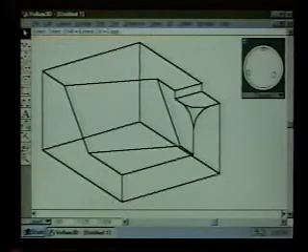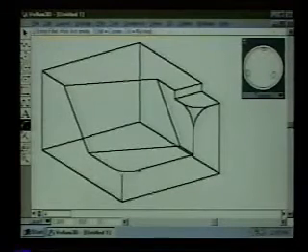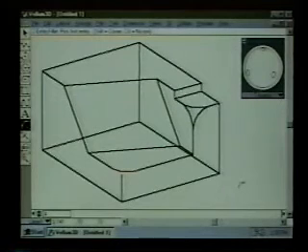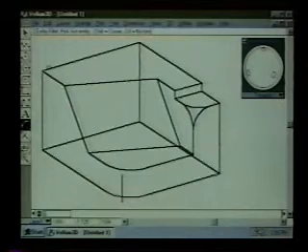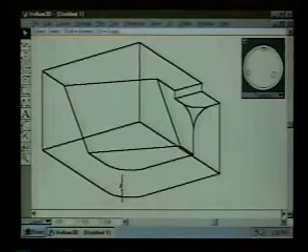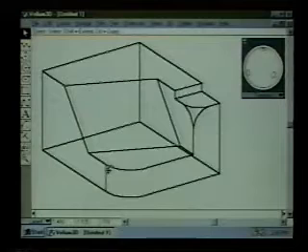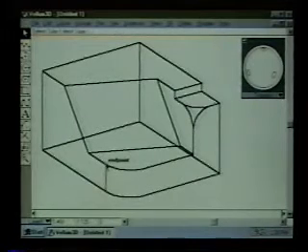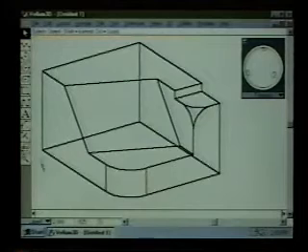And then let me put another fillet here, and we'll make this one be 0.6, and we'll do the same thing here. Now again, here's a line that I should take advantage of. Let's take that line, grab its endpoint, and put it right on the end of the arc. And then using the message line, it says control equals copy. So I could grab that endpoint, hold the control key, and move a copy of it over to that endpoint.